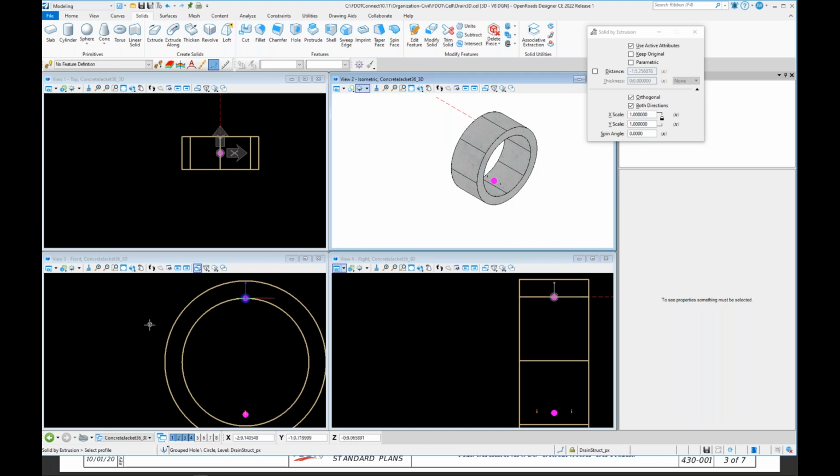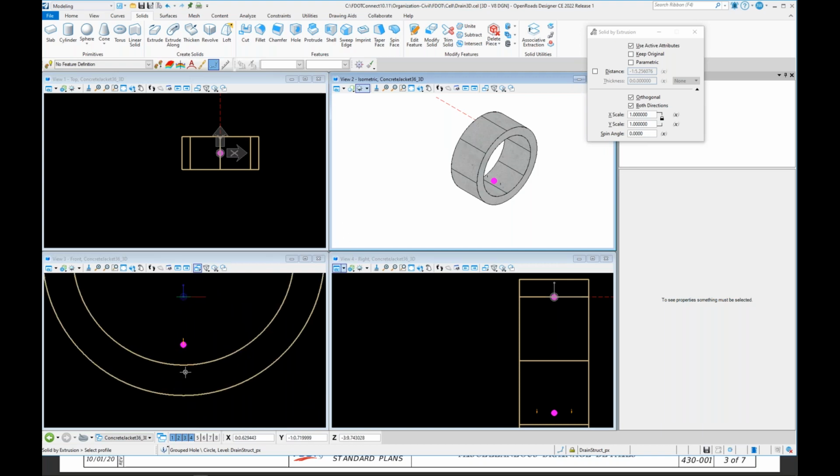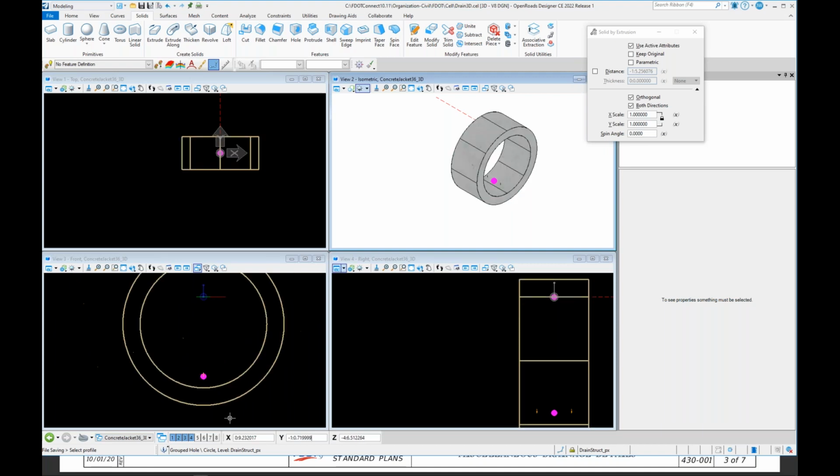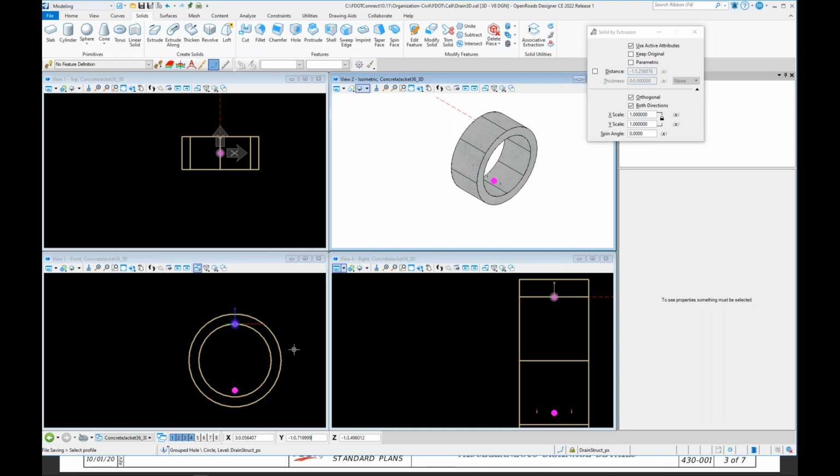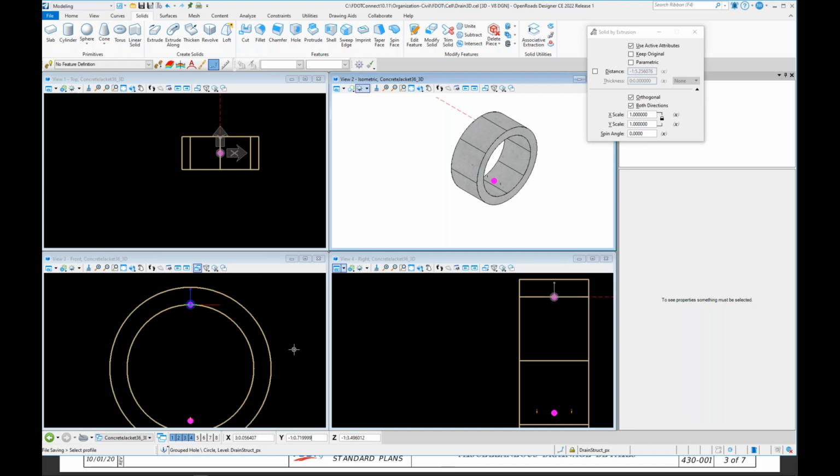Now, one of the things you're going to notice is these are not aligned with anything on the pipe jacket. Well, that's because we want these lines, or this point and these shapes, to be where the invert of the pipe will be that's coming into this. So you leave it set there and you don't move it to this point so that you can connect pipes to it and they align properly.